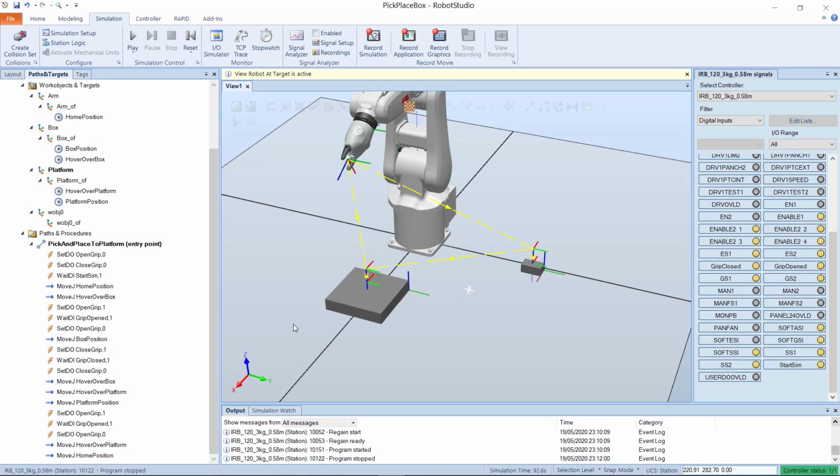If we are working with a real robot arm, the current programming is enough to actually do what we have designed. However, since we are working with a simulation, we have to design our own simulation scenario, where the gripper can actually physically hold onto an object, and where the gripper can physically open and close according to the input and output signals that we've set. This is where we introduce station logic and smart components to our program.